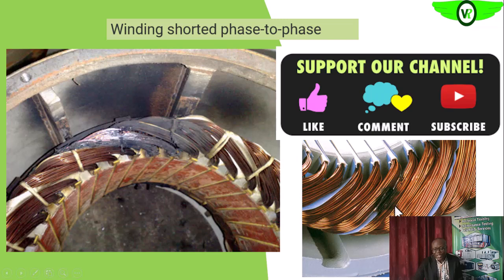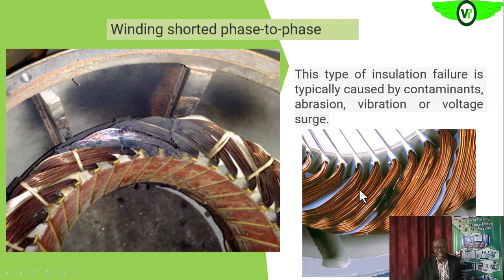Now if you look at this installation, and that is how all electric motors are wound, you see that insulating papers are placed in the stator before the windings are placed, which means the winding does not have any connection with the stator itself. Then if you look at these different phases, you see that this insulating paper is placed to separate this phase from this phase.